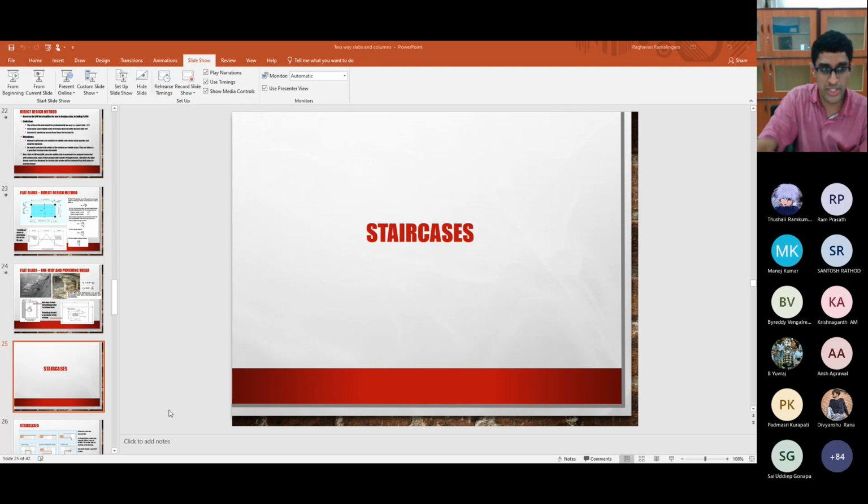But one good thing is in slabs, for most of the practical loads which you get, when you design that slab, you will get a very low thickness for the slab. So just increase it based on, say, a ratio of 20. Approximately what you can do is, if you're having a one-way slab which is simply supported,